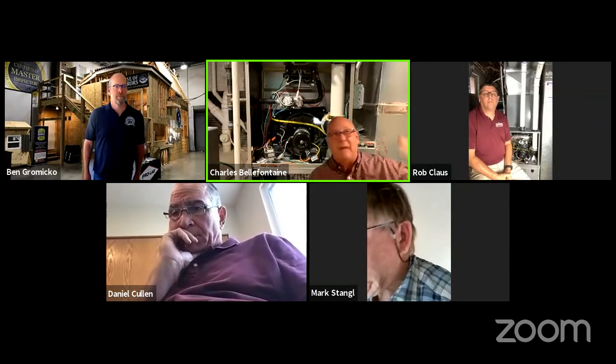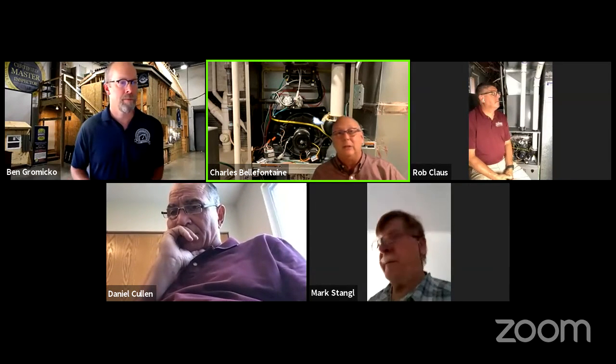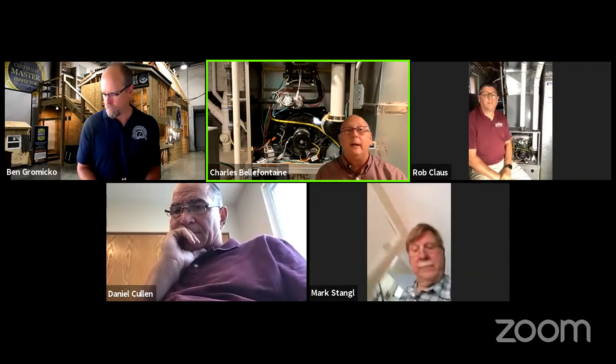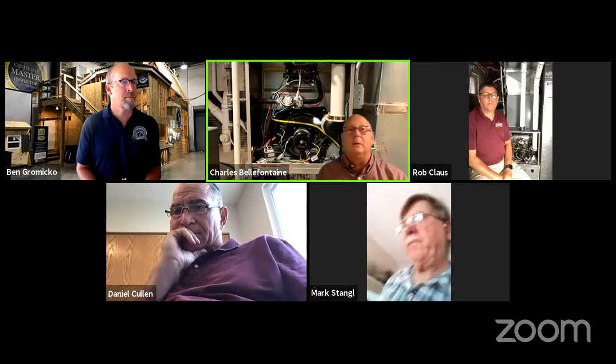That's going to be my high limit sensor. That's also going to indicate on the data plate when that turns the furnace off. Most of them are somewhere between 165 and 185 degrees. I've seen some of them up to 190. But nonetheless, if the temperature gets up to that high, then the whole unit shuts down. So if you have a hole in the heat exchanger, if my blower fan's not working, if I have a clog in the air conditioning coil, or my air filter is restricting flow, these are all things that slow the airflow going over the top and can cause it to overheat.